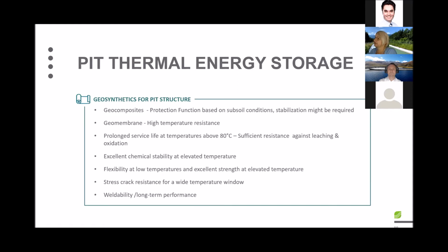What needs to be considered in addition is the thermal elongation behavior of the material, as waves could be created, and in the worst case possible bridges could occur. Thus, the material has to offer stress crack resistance over a wide temperature window as well. Not to forget the weldability of such material and the long-term performance of the welds in addition. So that is very relevant, and therefore materials have to be adjusted for it.